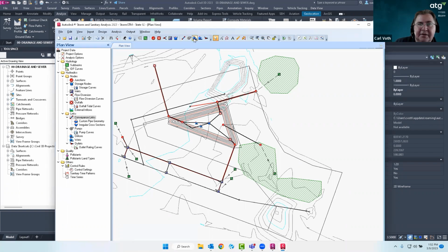And then also when we come from our ponds, here's where we need to add those orifices and where that's going. So if you're going just off site, we can just add that one there. And then we can connect from this point to this point. And now that is an off-site storage conveyance, in which case then we would need to come through and then delete out these as well.